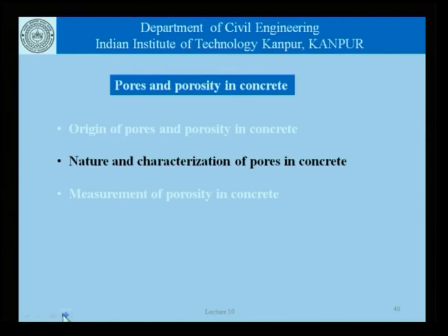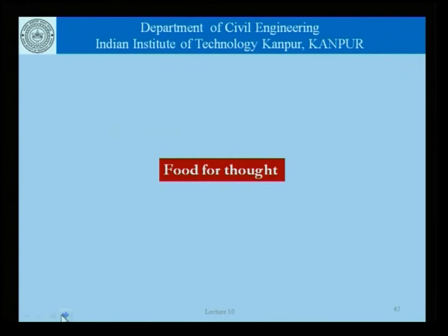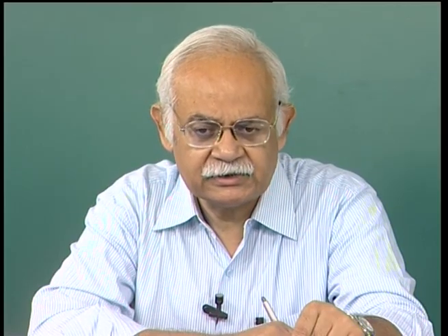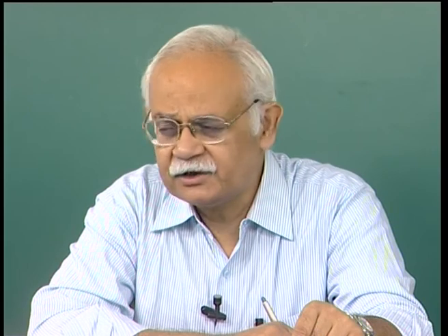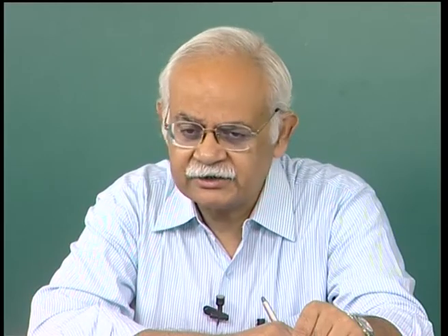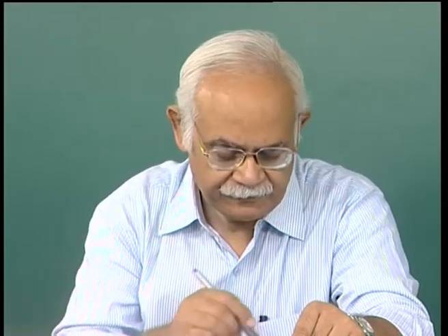So, having completed our discussion on the nature and characterization of pores in concrete, we need to talk a little bit about the measurement of porosity in concrete, and that is something which we will do in the next discussion. We will close the discussion today with some homework, and that could include study of hydration reactions from the point of view of associated volume changes. We did give two examples of C3S and C2S hydration. I would like you to look at those hydration reactions a little more closely and also try to understand what is happening with C3A and C4AF.